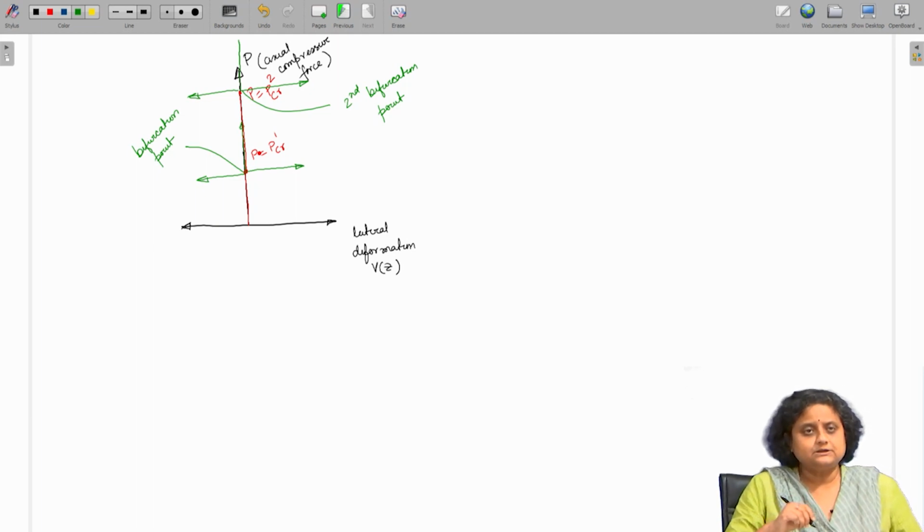So, if the axial compressive load is below the P critical value of the column, then the column is not going to deform at all. Now, when the applied load reaches the P critical, a different situation arises. Then the column can bend in either direction, or it cannot bend at all. It can skip that point.